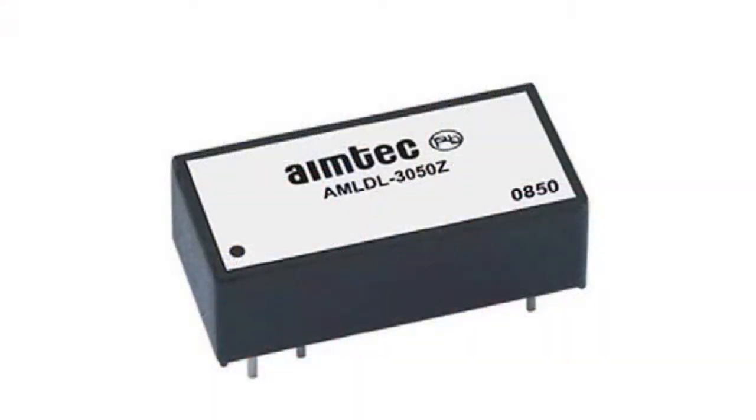The company AIMTEC has developed a new set of drivers for light-emitting diodes, AMLDL-Z. The construction is of DIP14 type of the cabinet for models with output current of 300 to 700 mA and DIP16 type of the cabinet for a model with output current of 1000 mA. A decreasing transformation topology is used in these drivers.